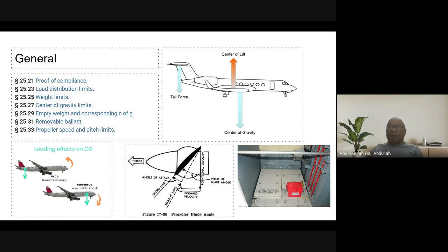And for aircraft stability, we always put the CG in front of the center of lift, because if something happens, we always want the aircraft to nose dive. For a stable aircraft, the nose always drops when you stall it, and then the stall will be almost automatically recovered. So that's what the rule is. Normally we put the CG in front of the center of lift. So that is for the use of aircraft maneuver, control, and stability.